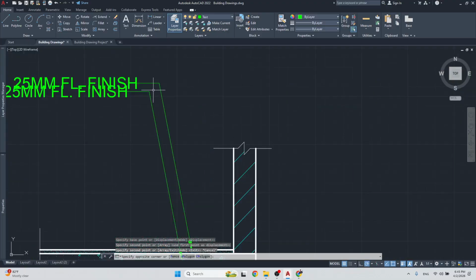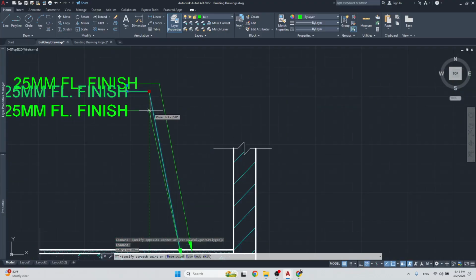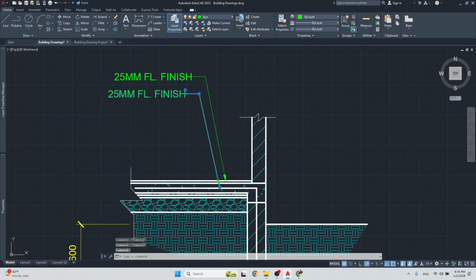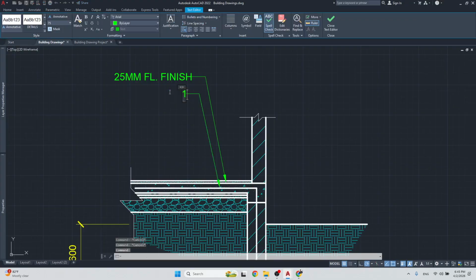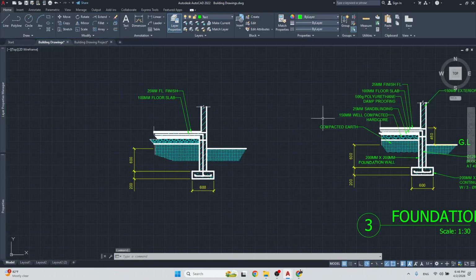And then I could just bring this down a little bit. So double click on it to edit it, and this is going to be 100 millimeter floor slab. All right, now this could be a 100 millimeter floor slab with whatever number, 65 BRC fabric, etc. There would be a BRC in your floor, concrete floor slab. All right, so we have that, and so on.